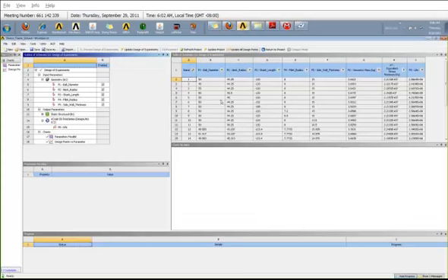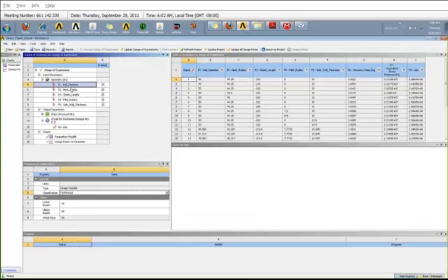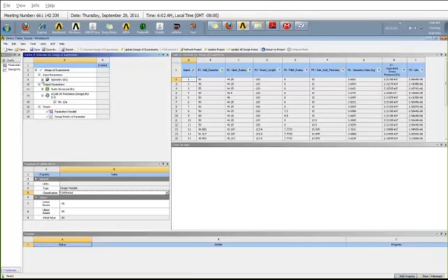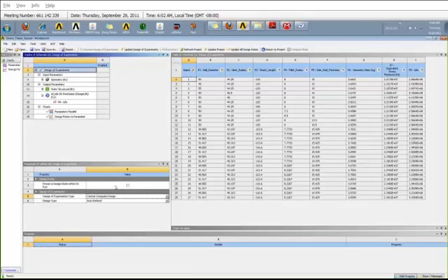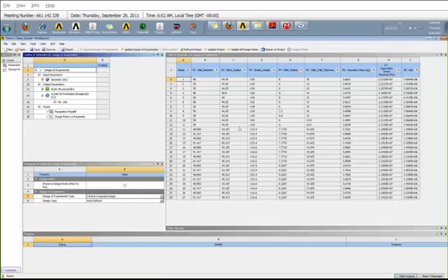Let's go back to my Workbench. So you can specify a lower and upper bound for each of these parameters to create the DOE matrix. By default, ANSYS creates plus or minus 10 from your initial value. So based on these 5 parameters, ANSYS created somewhere around 27 design points based on the default method called central composite design. It basically chooses the corner points and then some midpoints and also some points in the center. Once it has created this DOE matrix, I can hit update design of experiments. That will go in and solve each one of these design points.